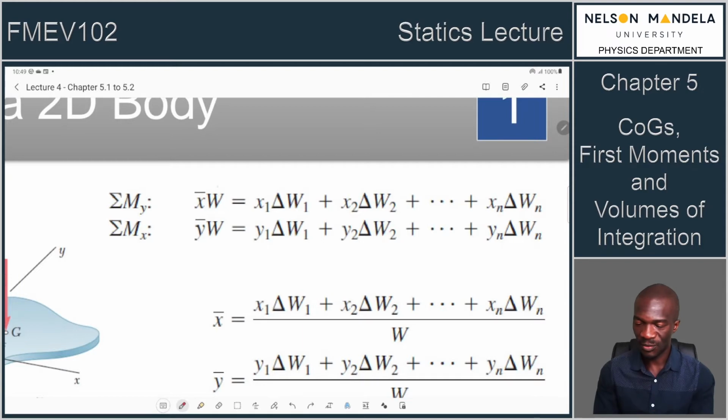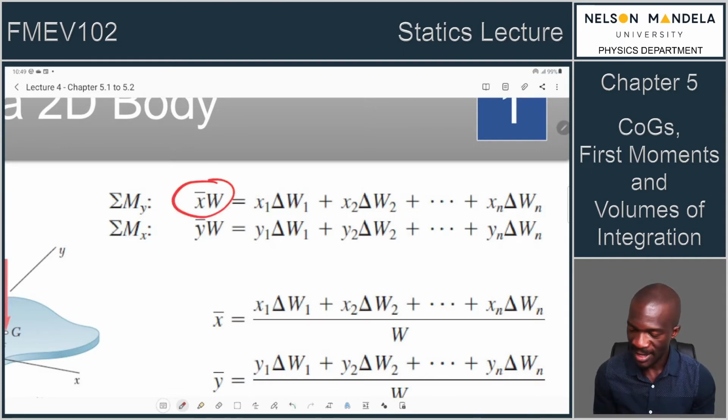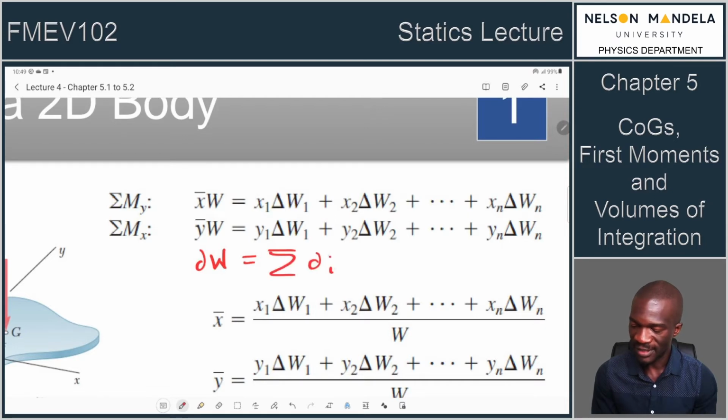Then this is the weight of the what? Of the resultant. We said from last time, this is equal to a sum of all the individual moments of the particles that make up the rigid body. This is why we have x bar weight is equal to x1 weight 1 plus x2 weight 2 and so forth. So in other words, you just have some distance multiplied by the weight is equal to the sum of the distance of each of the individual particles multiplied by its own weight for particles 1 up to n, or maybe small letter n, according to this convention.